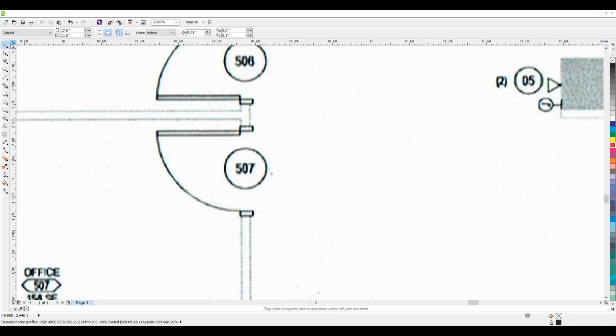But you don't need to guess. You can just come over here. As you put your mouse at the point where these two rulers meet, it'll turn blue or blue-gray. You can click and hold, drag it out, and you can see I now have a cross going across the entire screen, up and down. This is setting my new 0.